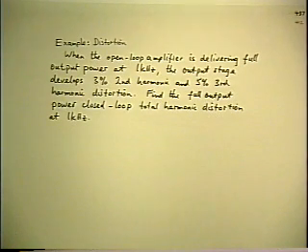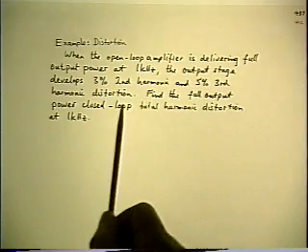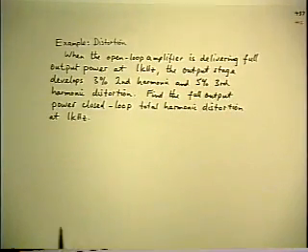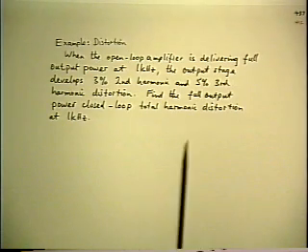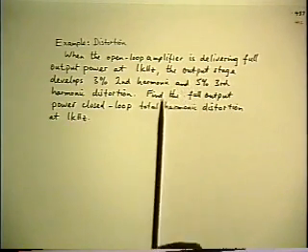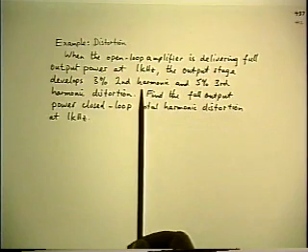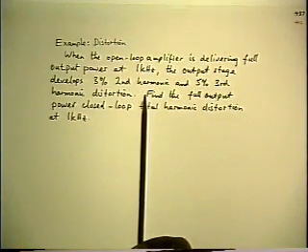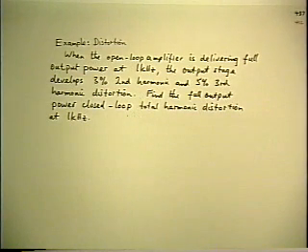The only thing to find out is, if this is what it develops, measured open loop, what do you get in the presence of the closed loop feedback? You have to compare the same reference condition. That is, you have to compare the condition when the output is still being driven to the full level, the same level at which you measured the open loop distortion. That's the only way you get the same distortion generation, and then you find out how much the feedback reduces it.